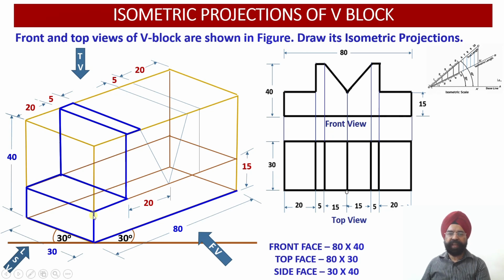So this is 15 millimeter high and 30 millimeter width over there. And then in the front view, you see we haven't drawn a dark line over here. It means this is an integral portion, so I need not join this dark. So we have to draw this vertical wall, and then this particular dark line we need to develop over here.